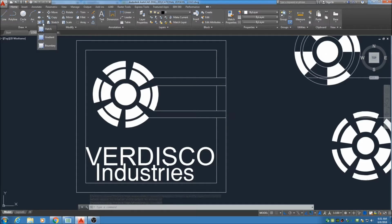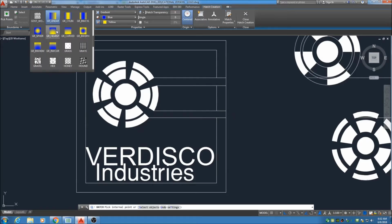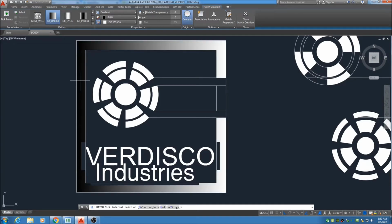All right, let's go to hatch, and this time we need to go to gradient. So how do we get back to gradient? Over here it says solid. We're going to use gradient. Now you could see I have these different types of gradients, and there is a big list of how they can be done. But I think I'm going to do this one where it goes from one color to the other. Currently it's set from blue to yellow, but I think I'm going to do black to white. I don't know if it's white to black or black to white, but let's try it out. Now if I float inside here, and I get my preview, I'm going to say, yes, I do like that.